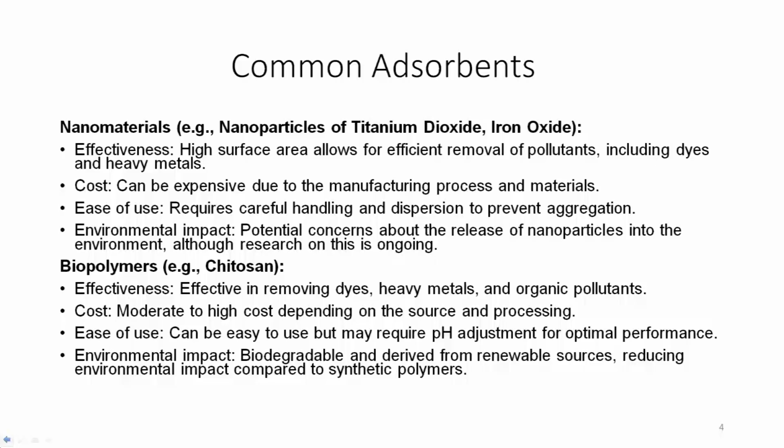Nanomaterial. Nanoparticles of titanium dioxide or iron oxides have been used as nanomaterials and are one of the common adsorbents. Effectiveness: high surface area allows the efficiency of removal of pollutants including dyes and heavy metals. Cost: can be expensive due to the manufacturing process and materials.